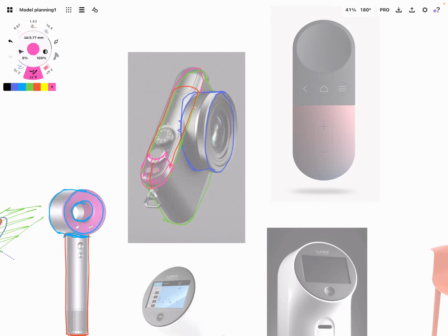And then to create this area here, that looks like it's an extrude. So I'd say just an extruded cut. So if you imagine this as a surface that's getting extruded through here and cut to give you the area around the controls. Okay, and this part line here, or this join, that's just merely the resultant of the intersection between the camera body and the lens.